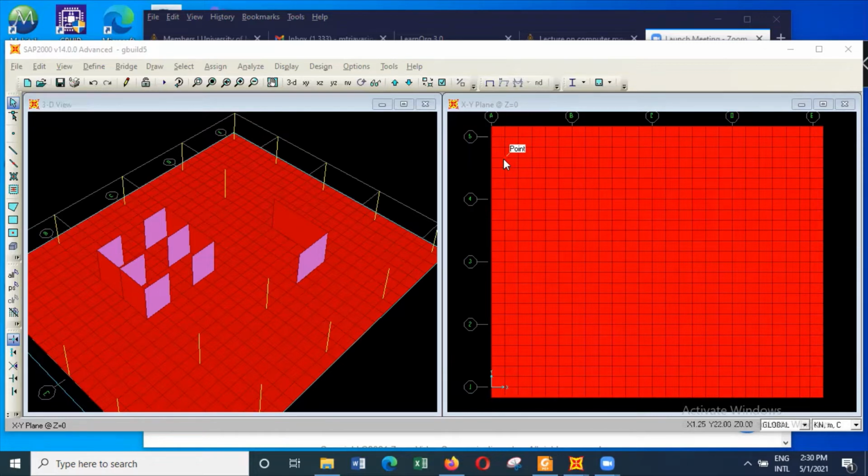And let's assume that we are having fairly dense sandy soil where we are able to go up to about 150 kilonewtons per meter squared. Then the K value, if you use a factor of safety of 2, and some engineers use a factor of safety of 3, we'll assume a factor of safety of 2. Bearing capacity is 150 multiplied by 40. So you get a spring constant of 2 into 150 into 40, which is 12,000 kilonewtons per meter cubed.